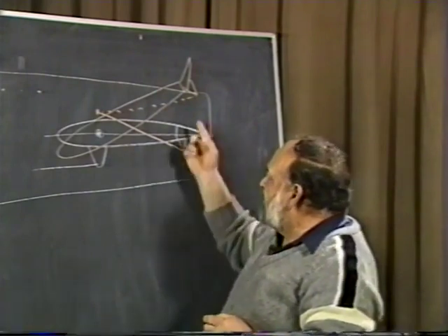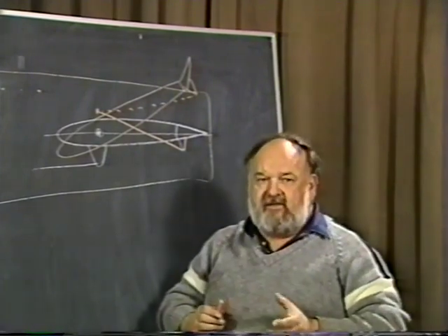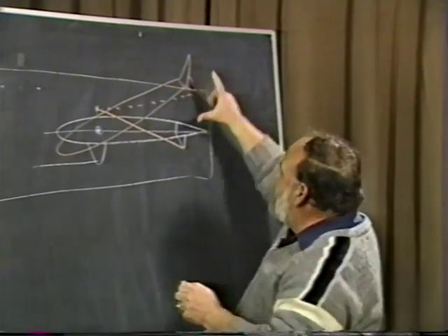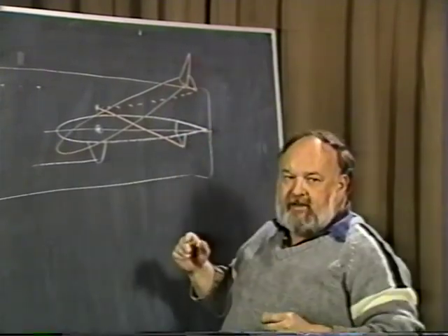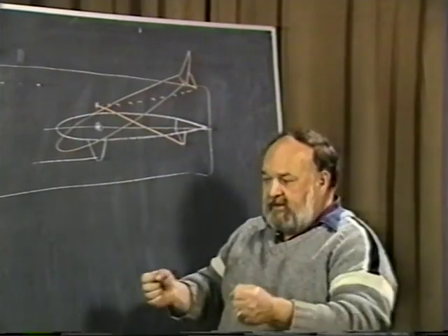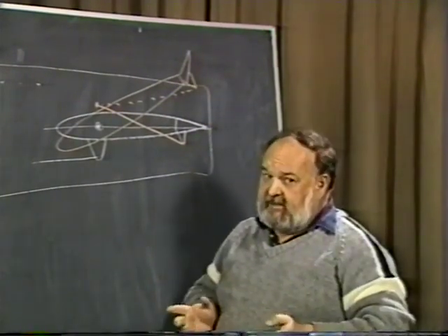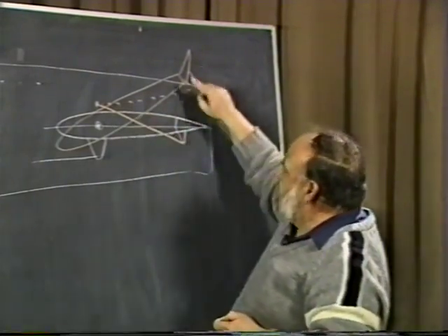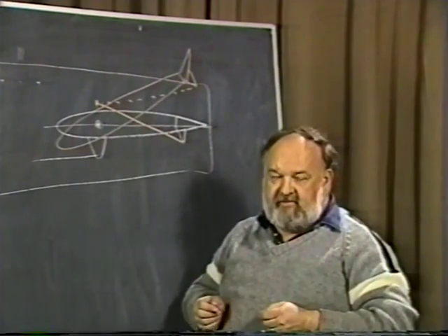What is sort of nice about this kind of design is that you can almost dial in the stick forces you want. If you want your stick to be real heavy, make your tab big, or make the chord of it big, or make the linkage such that it really moves the tab an awful lot. And boy, that surface will be heavy as can be. On the other hand, if you want it real light, you can change your linkage here, make them smaller, so the tab doesn't move very much, and that'll make it very, very light.